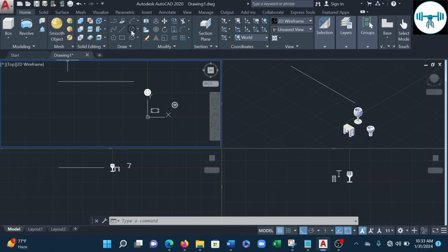Now the profile we said is a circle, so I'm just going to draw a little circle here. Good. Like I said, I'm not so keen on dimensioning right now. So I have my profile, I have my path. Now we go to sweep. So I'm going to select the sweep operation.